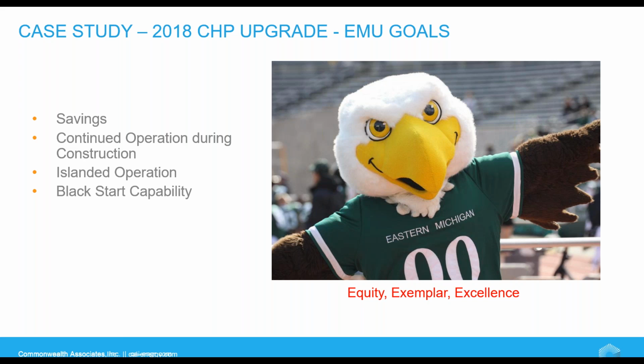Third, while they do typically import a portion of their electrical needs, they did want the ability to operate in island mode as a backup for resiliency to outside forces. They didn't want to be held to the local utility's ability to provide power when severe storms hit. And lastly, they were also looking to add black start capability to allow a restart if they were in island mode and no outside power was available.